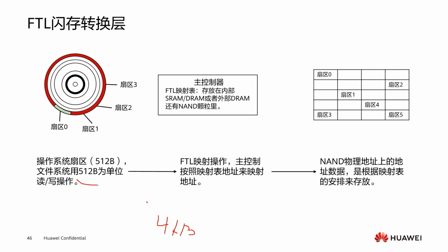In order not to increase the burden on the operating system, the SSD uses software to virtualize the operation of flash memory into independent sector operations of a disk. This is FTL, because FTL exists between the file system and the physical flash medium. The operating system only needs to operate on LBA as before, as with all turntable work. From LBA to PBA, everything is handed over to FTL. It is because of FTL that NAND Flash can be used as a hard disk, and the file system can directly use the SSD as a common block device.